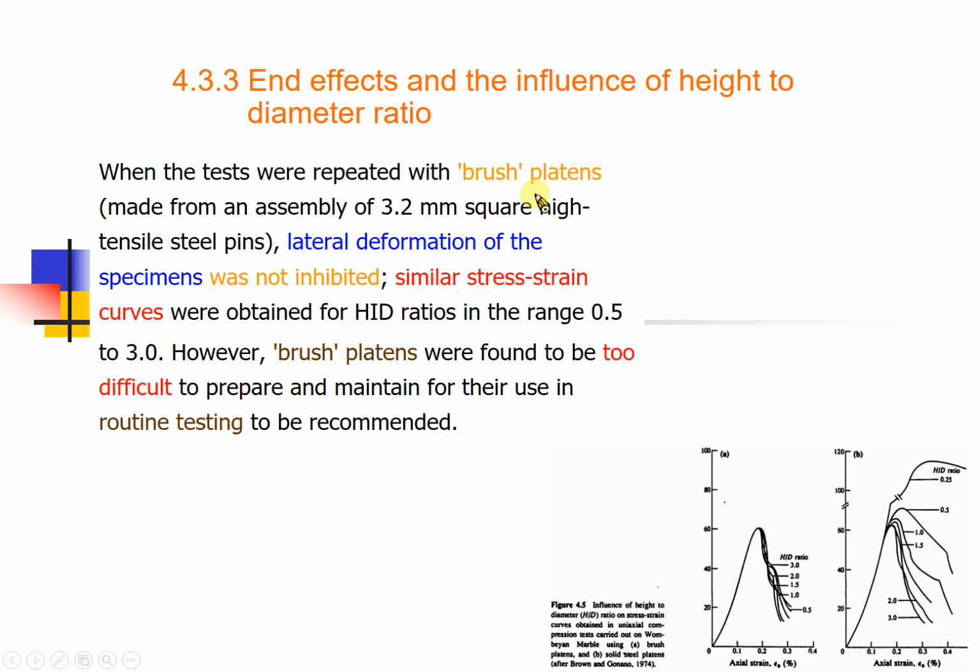So it is not recommended to use those ways to reduce the friction. The standard will only accept mechanical polishing of the sample. That will be the only way to treat the sample to minimize the so-called end effect.